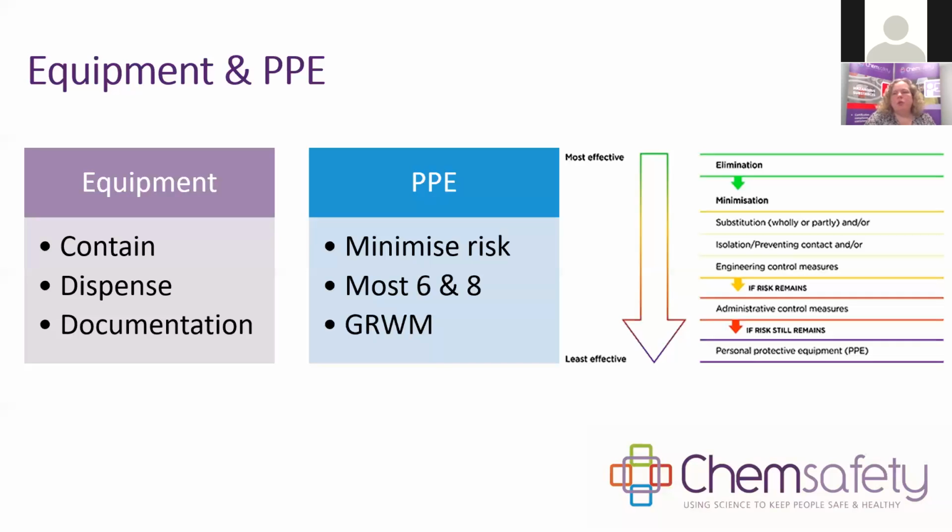You do need to make sure that you have selected the correct type of PPE, both for the substances that you're using and the exposure scenarios that apply. And if it's complicated, particularly with inhalation hazards, you may need the input of an occupational hygienist. You should be able to show with confidence that the PPE you're using is appropriate for your situation. You also need to make sure that workers know how to correctly use and maintain any PPE they're given. So again, looking at respiratory PPE, make sure you've got a good program in place for fit testing, for changing filters, and for maintenance of those.